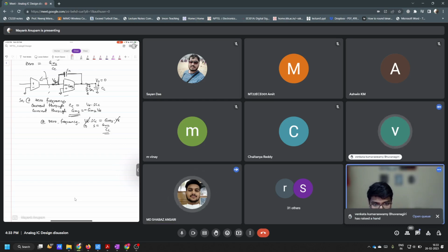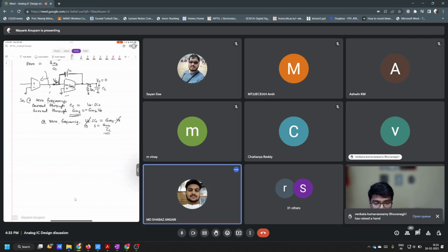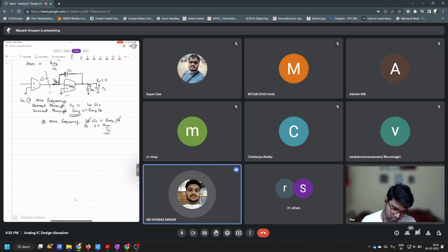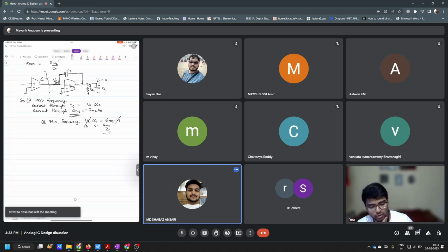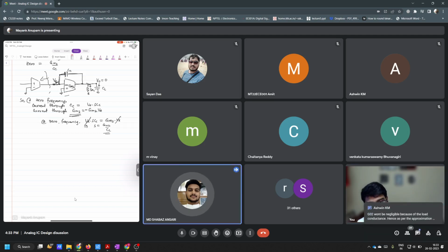Sir, I have a question related to week 5. Yeah, go on. Sir, in the last lecture, you told that if you add a resistor divider for the k gain, then the positions of poles and zeros are not changed, but the omega u loop is changed. Yes, correct. And the phase plot is also not changed. The phase plot will not change. Yes, the phase margin will change.